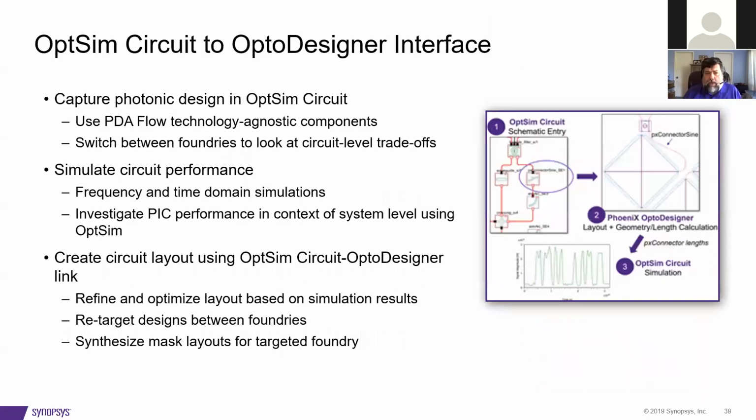We also have another tool that came out of the RSoft team called OptSim Circuit. This is a way of doing a schematic layout of your optical network system, and you can put devices in there, okay? So you can put an amplifier, or you can put a source in your fiber network, and you can build up the network and see how the optical signal goes through the network and comes out the other side.